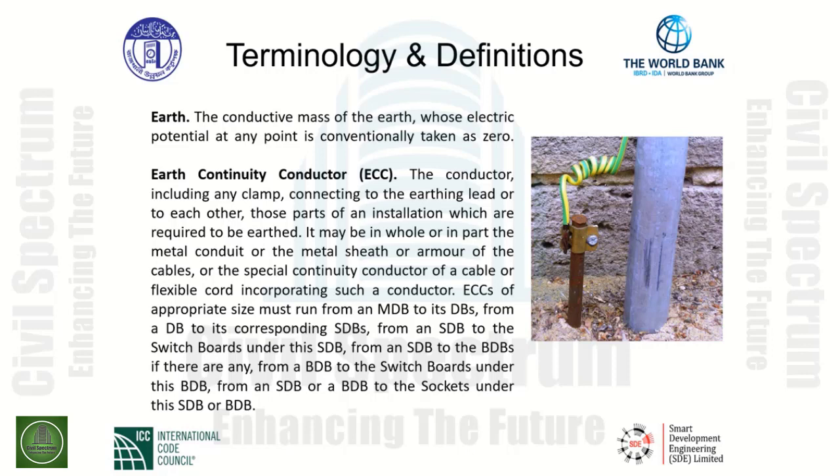Earth continuity conductor, abbreviated as ECC, is the conductor including any clamp connecting to the earthing lead or to each other, those parts of an installation which are required to be earthed.